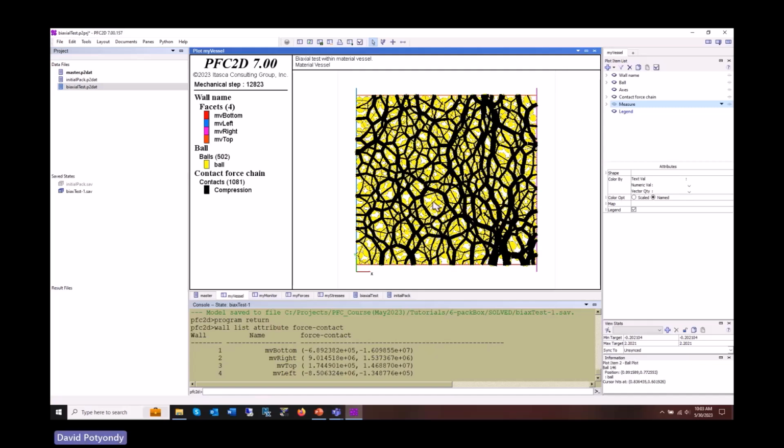And so when we actually do our triaxial tests on our real synthetic specimens, we're going to be measuring stress both by taking the external boundary, the platens, divided by the area, and we're also going to be measuring stress internally to the system. The one that's coming from the platens can be directly compared to what you measure in a true triaxial test in the lab, right? But in addition, we can measure what's going on in the middle. And when localizations start to occur, the stress in the middle is no longer uniform. It's not the same as the stress on the platens, and we'll be able to watch all that develop. Okay.